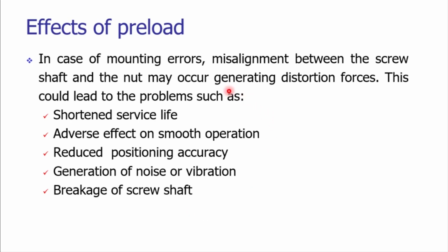So it is very essential when we apply the preload, when we apply the shim plates, and when we apply the tension in the nuts, it should be in a proper condition with due care.